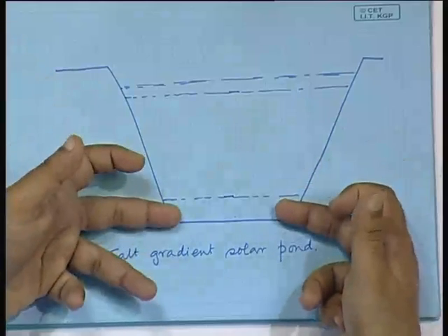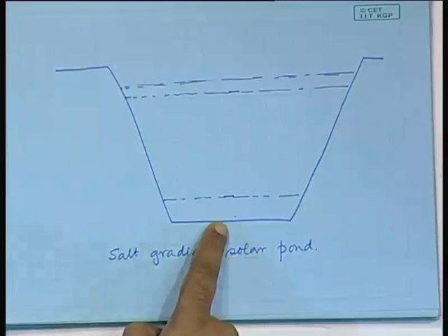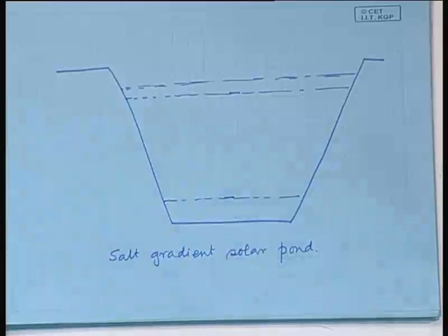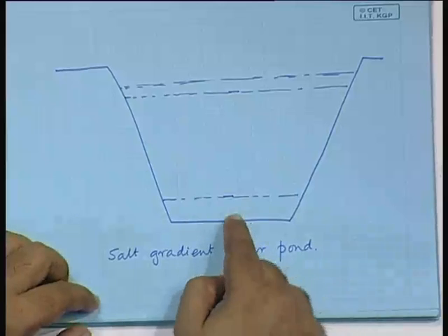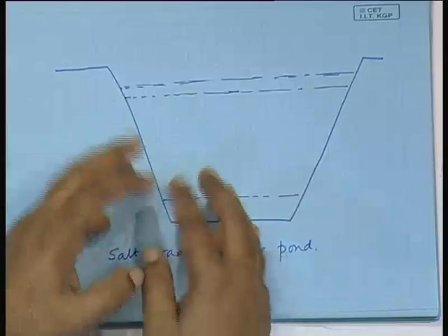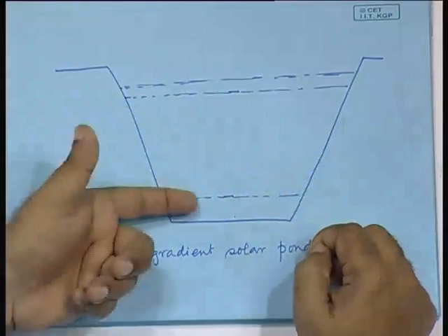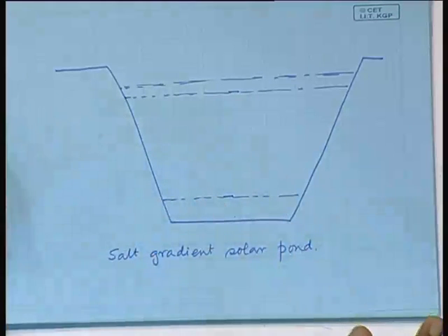So in order to use this energy you have to either pump up that water from the bottom, or you have to have some kind of heat transfer pipes in this part which take the heat away, either of the two. And in many of the installations that are there, this water is pumped up, and as a result it will tend to mix, and so as it is pumped up you will have to again re-inject very high density water in this part. That is all.